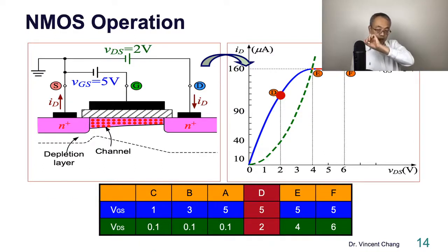So from source to drain, the voltage drop is getting smaller and weaker, and the channel becomes kind of tapered and shallower. This kind of structure tells us the linearity is broken. So the current is kind of going downward. The increase is a little bit difficult. It's kind of being limited.